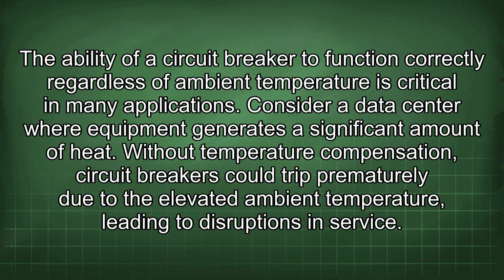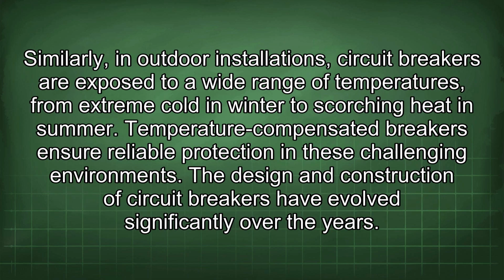Consider a data center where equipment generates a significant amount of heat. Without temperature compensation, circuit breakers could trip prematurely due to the elevated ambient temperature, leading to disruptions in service. Similarly, in outdoor installations, circuit breakers are exposed to a wide range of temperatures, from extreme cold in winter to scorching heat in summer. Temperature-compensated breakers ensure reliable protection in these challenging environments.